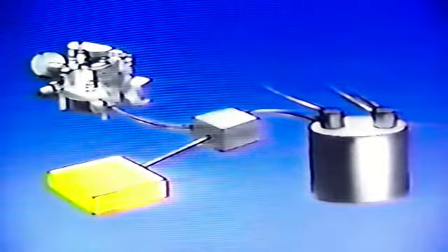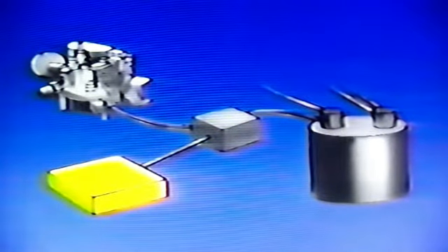Evaporative systems have been on cars for the last 15 years or so, and they perform vital functions in cleaning up emissions. The canister system takes care of about 20% of the pollution, and the PCV valve another 20%. Together, these two simple elements do almost as much work as the rest of the system. That's why it's so important to have a properly working canister.